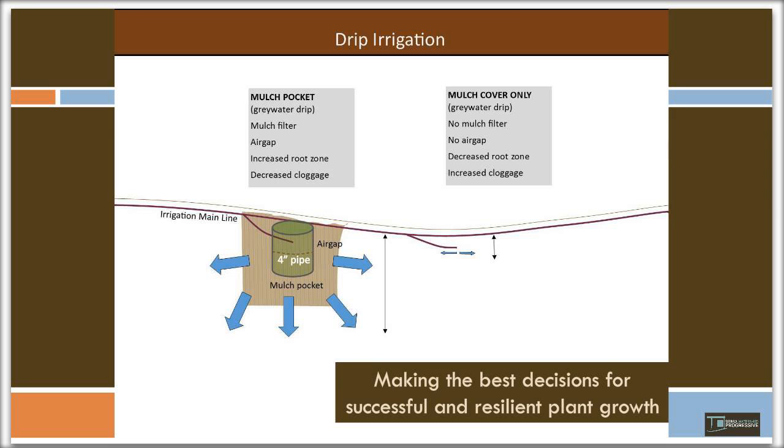The difference is a lot of other groups will use drip irrigation line, and it really just sits on the surface. We've done that a couple of times, and it seems to just run off like normal drip irrigation. We found this so effective that we're using it in our drip irrigation for potable water as well when possible. This is just another earthwork. It's a little bit more work. You spend maybe 12 inches down and 12 inches over to provide this mulch pocket, but it's highly effective.